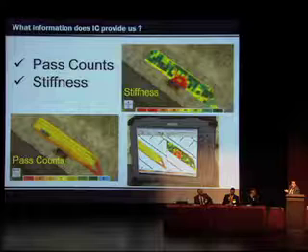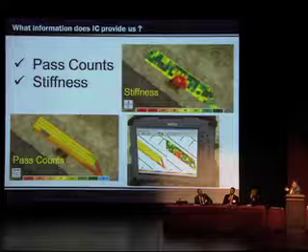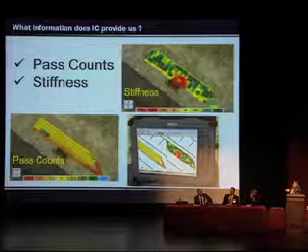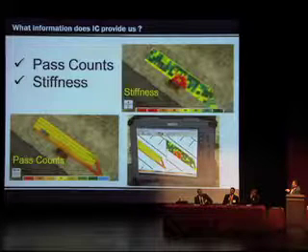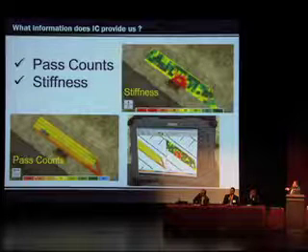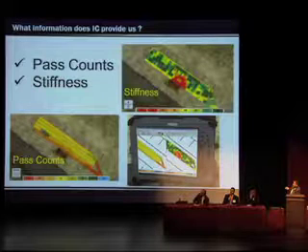You can see that on the on-board computer display panel. This is one example, a Ham technology, where you can actually see both at one time. On the left is the pass count, color-coded, so the first pass is red and yellow is about four passes, so you can clearly see that on the board.